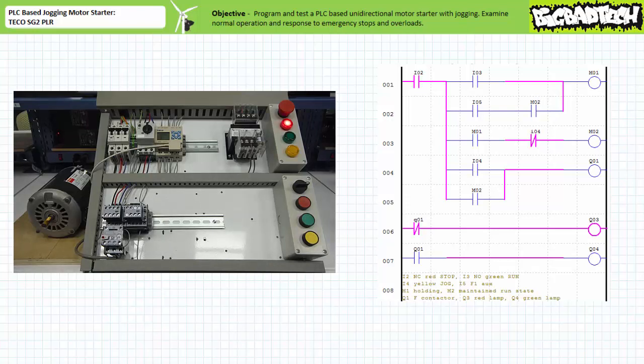As previously, when an operator presses and releases the green run push button on input 3, the maintain run state is asserted. While in the maintain run state, opening the e-stop directly depowers both the field input and output devices without reliance upon any programmed instructions to do so. The F contactor coil is de-energized, the F primary contacts open, and the motor turns off. When the e-stop is reset, the system returns to the deactivated start state and does not immediately resume operation. The system seems to correctly respond to an emergency stop condition.